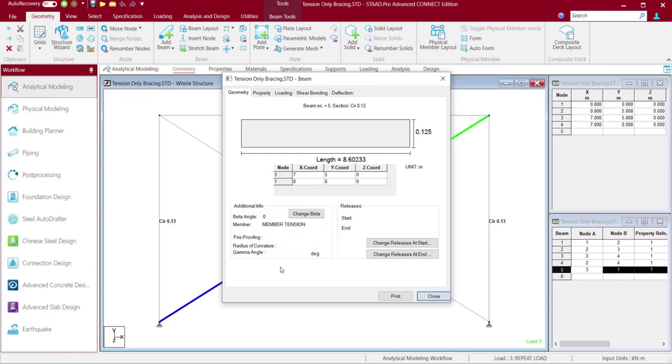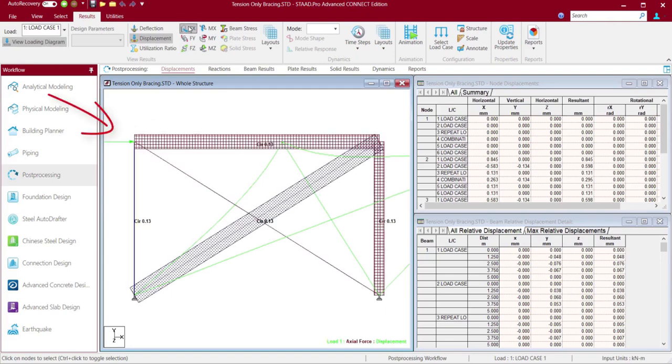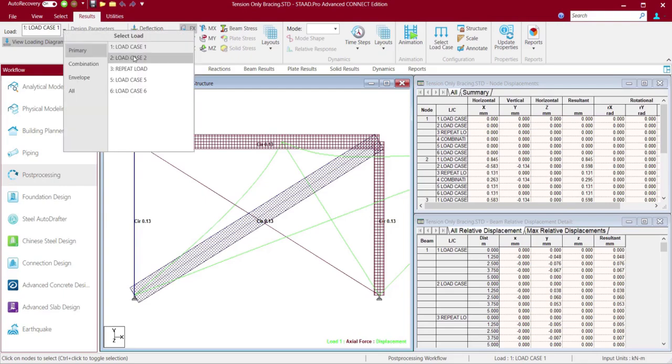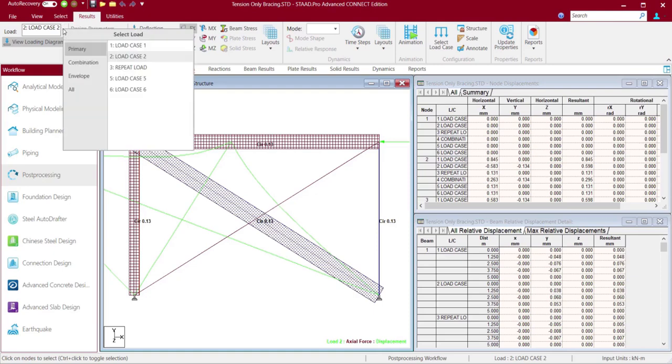Now you can see that when we are applying the load from one particular end, one of the bracings is experiencing the tension and another bracing is not experiencing any force, because it is tension only, and the moment it is experiencing compression, it is switched off. Okay, now go to another scenario when the load has been reversed and applied to the other, opposite point. Now this time the other bracing is experiencing the tension. Fine. So till now we are okay.